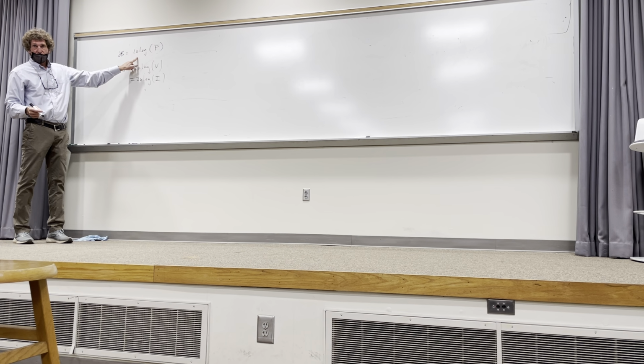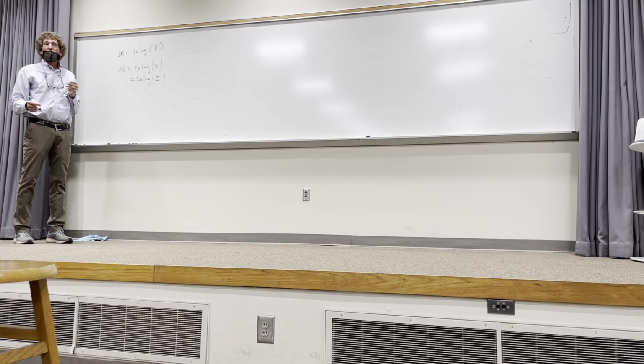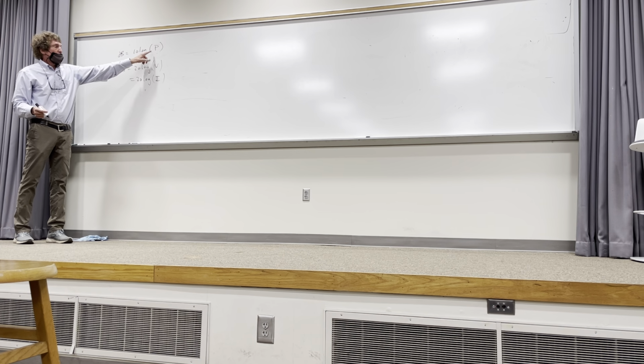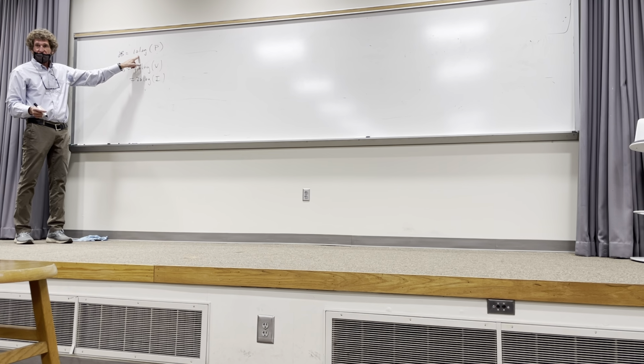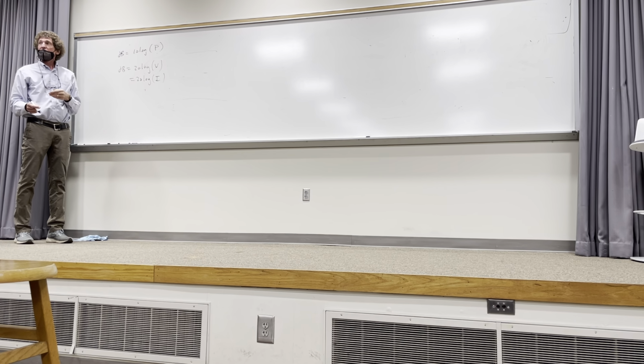Now, some people will wonder why. Well, power is always related to what? V squared, right? Isn't it related to the voltage squared or current squared? Think about that. You put V squared here. If you take the log of V squared, the 2 comes out in front, it becomes 20. Do you all see this? These two, the dB difference in a signal, if it's power or voltage, will be the same. And you'll see that a bit more clearly.